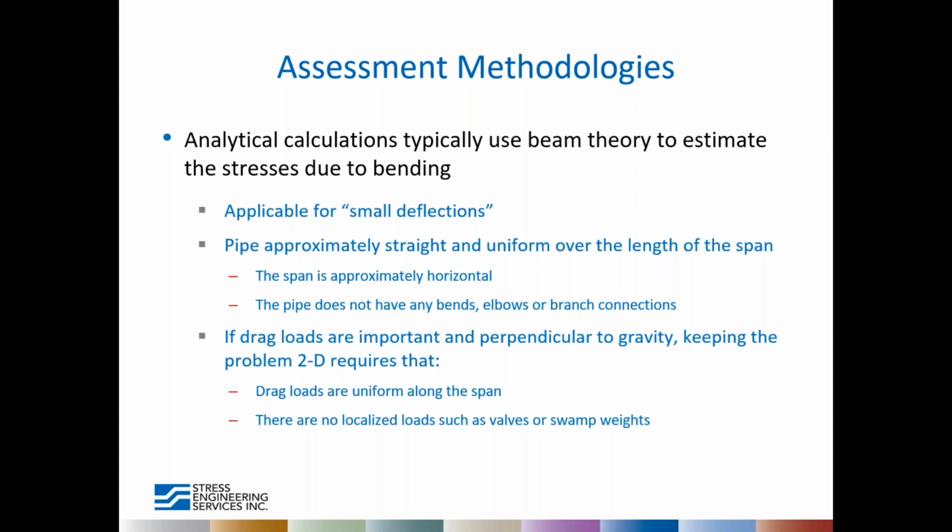Do you need to keep the analysis 2D for an assessment? No, you can still use beam models for 3D analysis, but when you reach a certain level of complexity, it's often just easier to switch to an FEA analysis. And if you do need to include specific details for an individual span, you've pretty much lost any benefit of an analytical method anyway.